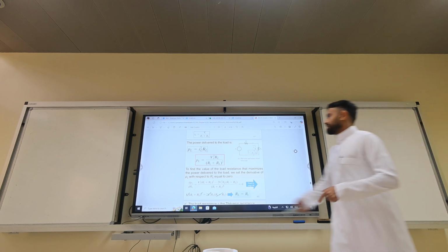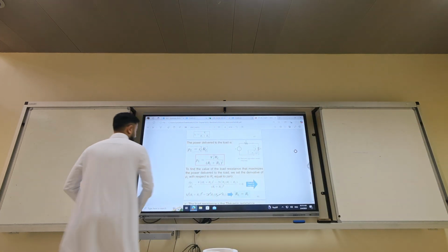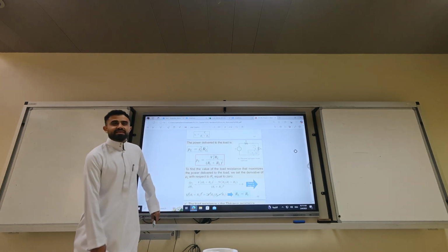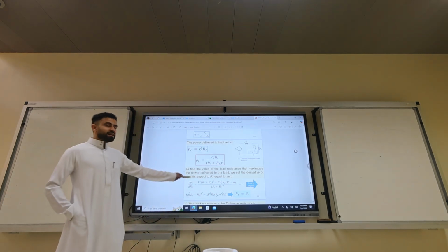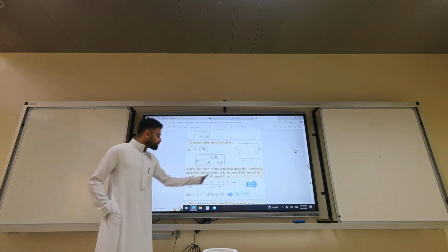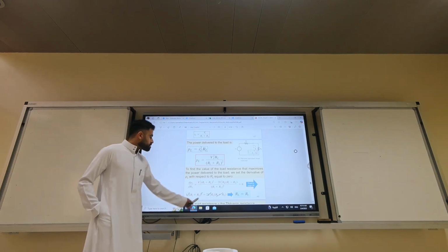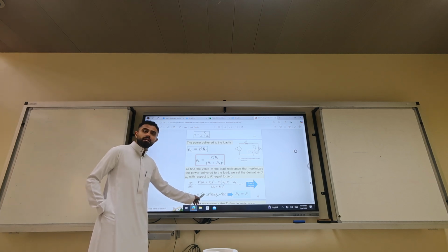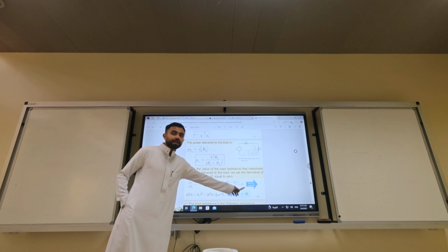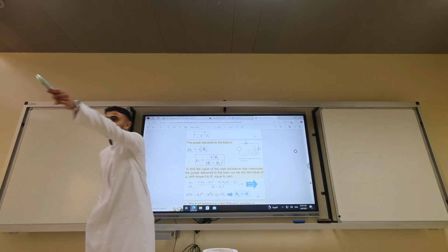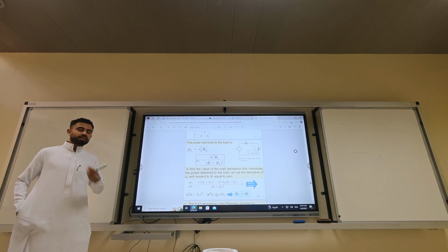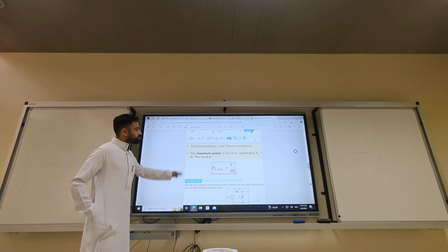So the quotient rule. You square the denominator. What's important is once you do the equations, you will find RT plus RL equals 2RL. This implies RL should be R Thevenin. And you got it right. So R Thevenin is the one that gives you the maximum power.